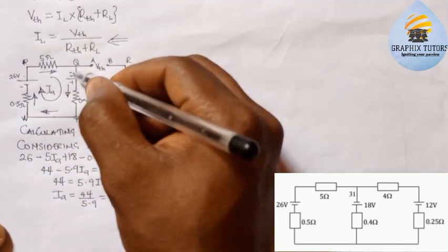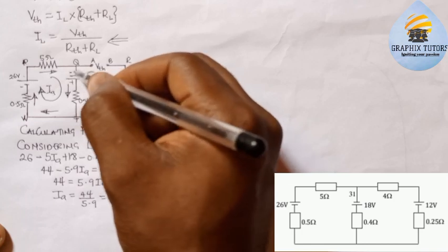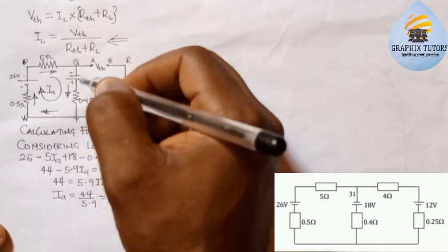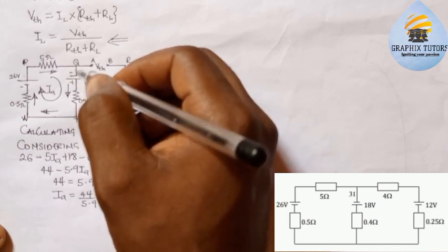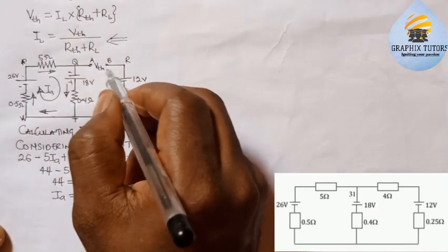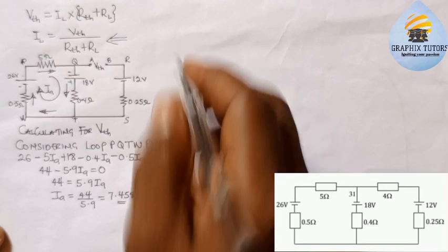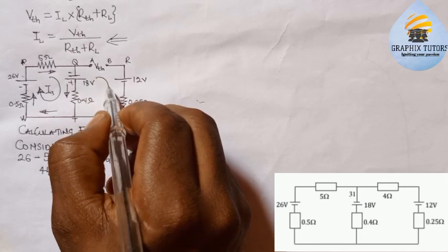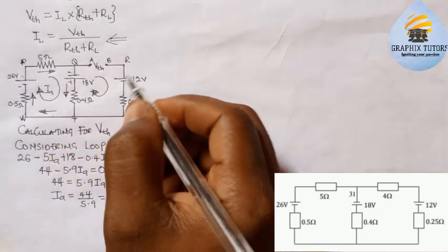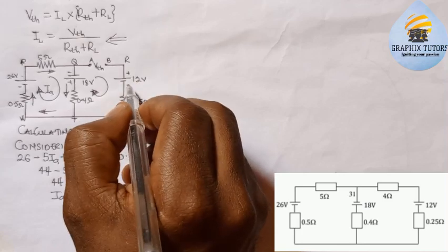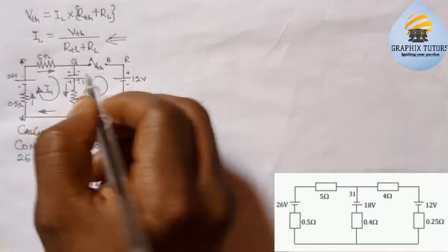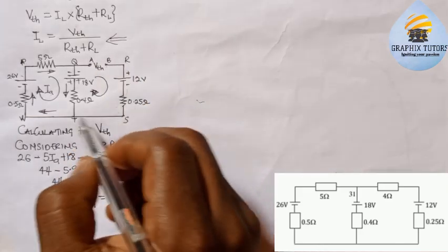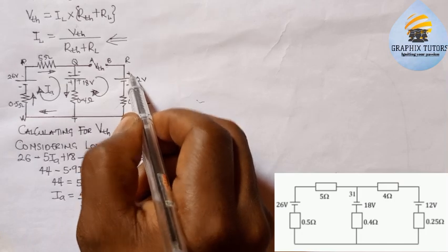Now if you notice it, current will tend to flow from a lower potential to a higher potential, right? So I can go in this direction or oppose it, depending on what you actually want. If I go in a clockwise manner, the way I went for my first loop, don't forget the longer one is positive, shorter one is negative. So I'm moving from here in this manner. If I move from higher potential to lower potential, it will be negative.